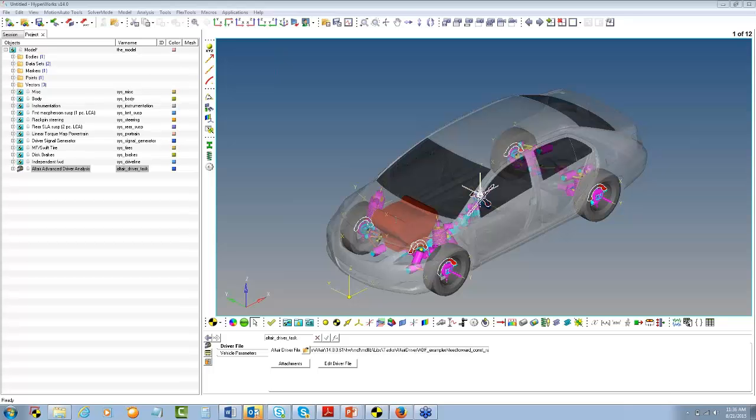All right, as I mentioned, the KNC event sums up all the events. First it runs ride, then it steers, then it does roll. So it is a mixture of all the events, and it takes a long time to run. I think it runs for 80 seconds. How do we calculate lateral acceleration? You know the radius, your path radius, and you know the velocity the vehicle is going to follow. So V squared by R is the lateral acceleration.